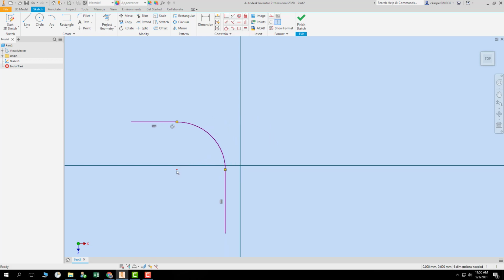Okay. I'm just clicking and holding the dot and kind of shoving the whole thing over. Yeah, I can adjust it a little bit here, a little bit there. Perfect. Okay, so that's what the arc tangent does, is it draws an arc between one or two points. It doesn't have to have a second one. It can just be one by itself. There, I'll trim it off. Trim it, all trimmed. Hit escape to get out of trim.